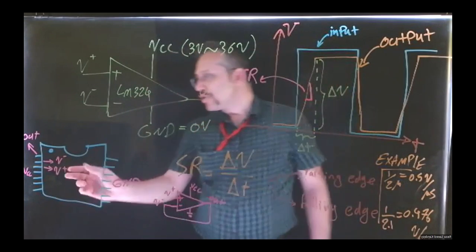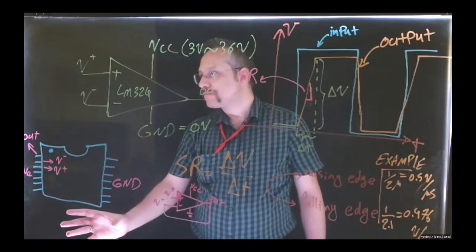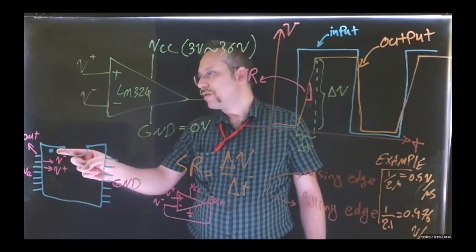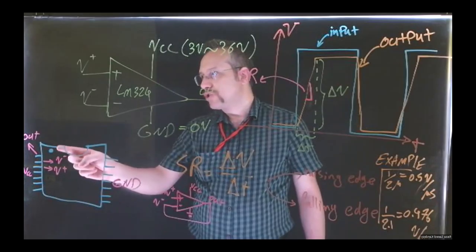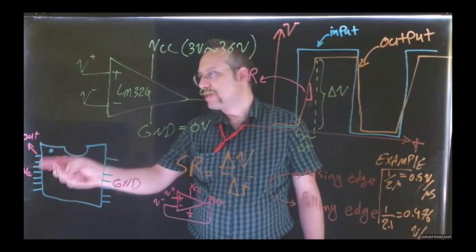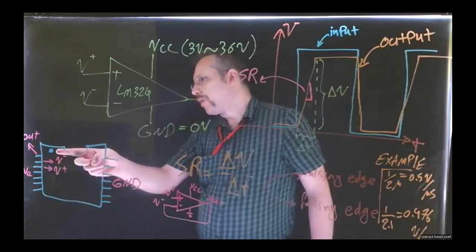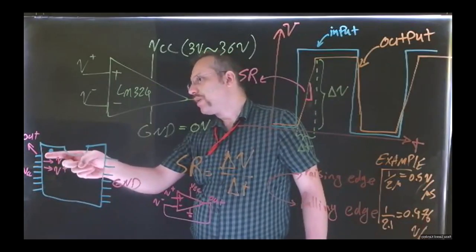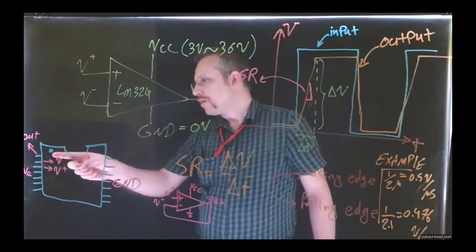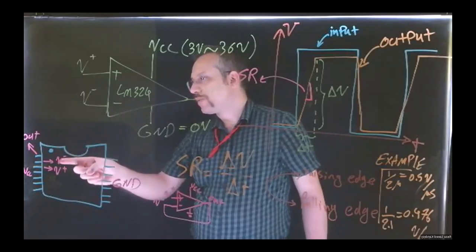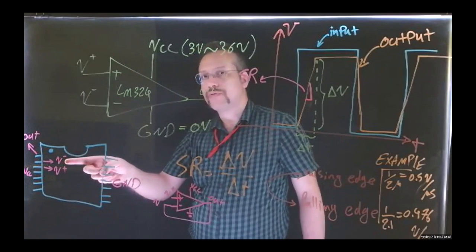Now, an actual LM324, as we saw before, looks like that. We have a dot on one of the edges. This is for recognizing and identifying which pin is which. From the dot, this is a 4 op-amp package, and you want to use one of them. The first pin is the output of the first op-amp. The second one is the inverting input of the op-amp.